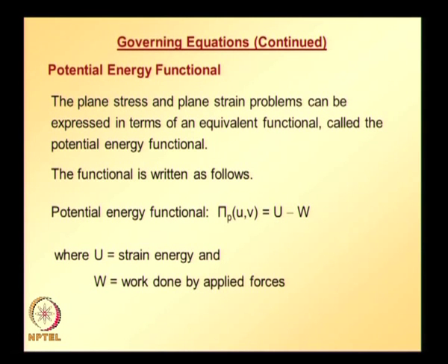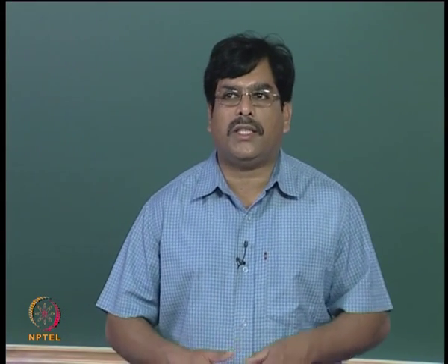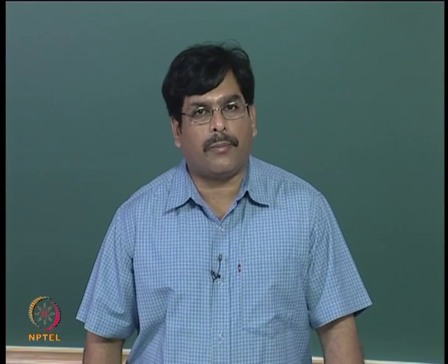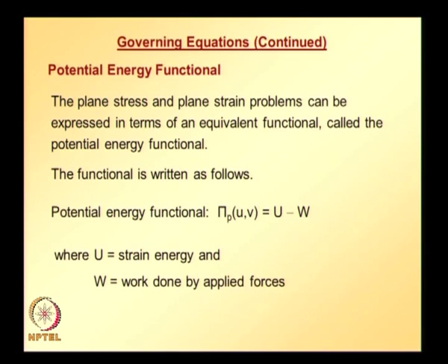So, finally, when we start with the governing differential equations, the two coupled equations in terms of displacements, and apply the essential boundary conditions and natural boundary conditions, and do all the process that we went through in the earlier cases, finally we arrive at this functional. So, this functional is directly given to us now. Now, our job is to check, verify whether this functional is the correct functional for the 2D elasticity problem or not. So, now let us look at how strain energy is defined.